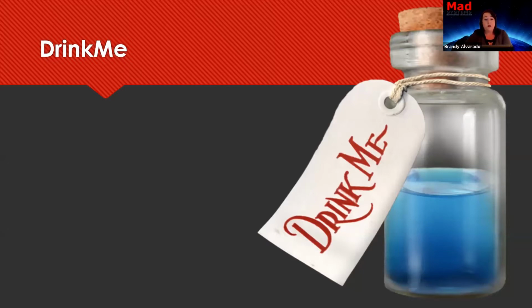With DrinkMe, you start with a plan view of your venue, add all the peripherals that you want, including projectors, monitors, lighting, speakers, amps, and anything else you might need. You then add all the media, real or dummy files, and then add the QuickSilver components that you want to drive that system. Once the drawing is complete and it contains all the equipment that you want, you simply press the Create button to generate the system.